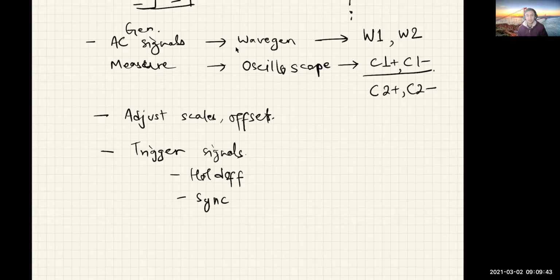And the beauty of the sync signal is that if you trigger the oscilloscope on a sync signal, then all of the signals that are being generated by a function generator are automatically synchronized to it and properly triggered when viewing on the oscilloscope. Okay, so those are the key circuit measurement techniques that you've learned so far.